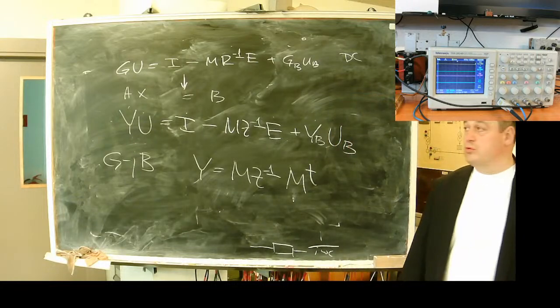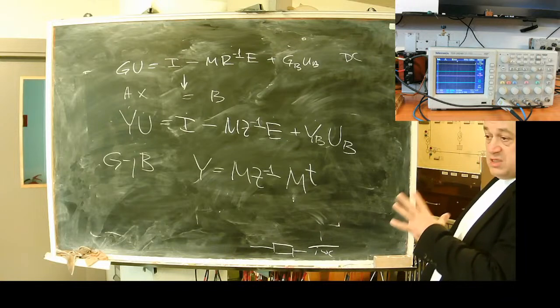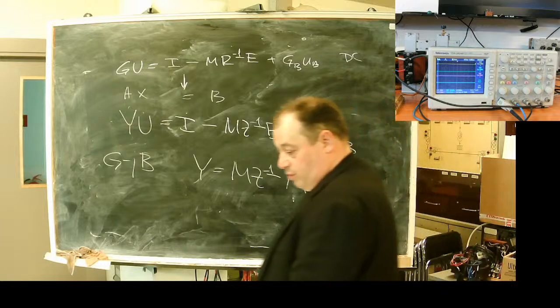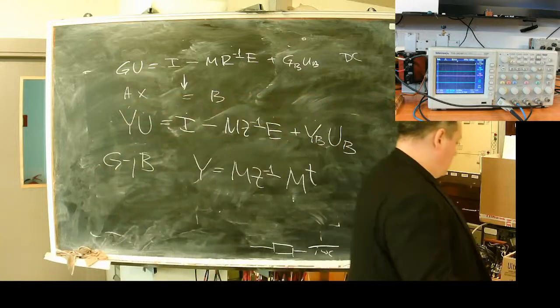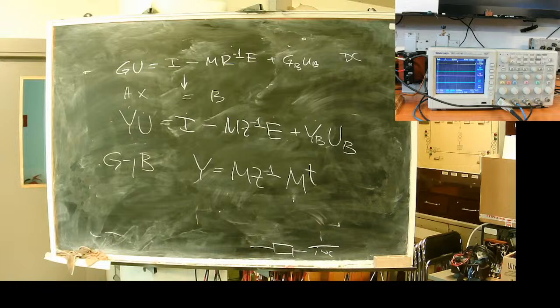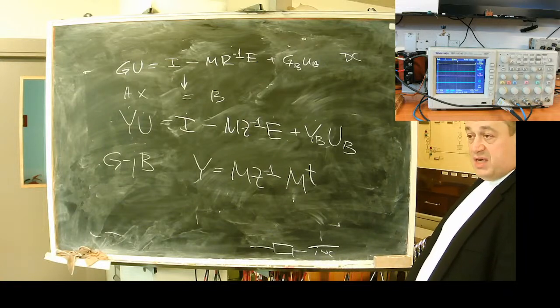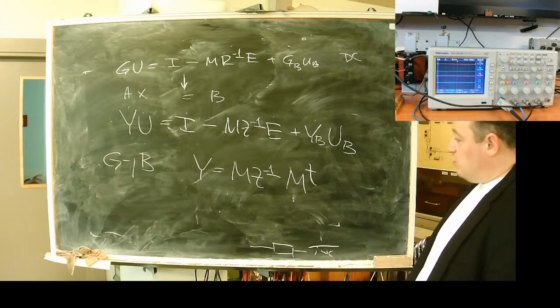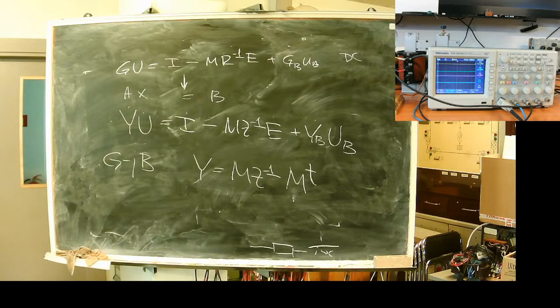In SciLab, I think we'll go with SciLab, but first we need to understand a simple idea of symbolic, or Heaviside technique, to assume that sine wave voltages and currents are projections to the imaginary parts of some vectors, and what we can do is apply Kirchhoff and Ohm law to these complex values. And everything will be fine.